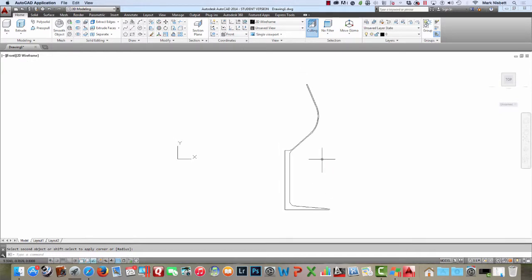So here's our wine goblet profile, and so you can see its thickness and the wine stem and all that. This stem looks like it's going to be fairly large, so you can stretch this out afterwards, kind of stretch it. So something like that. That looks a little bit better. So I'll do a region, and I'll just select it all, and it says one region created down here in our command line, so I know I'm all set.